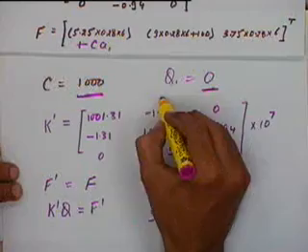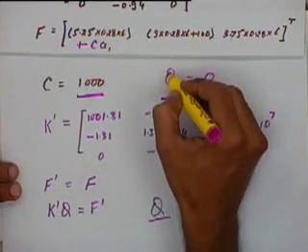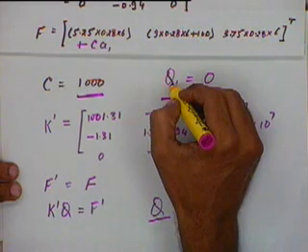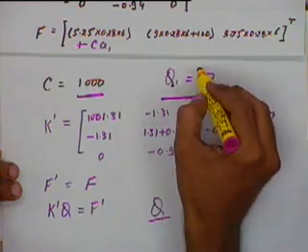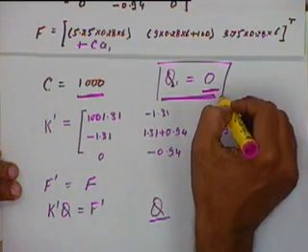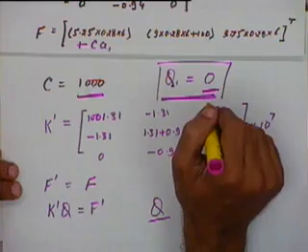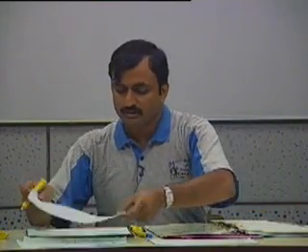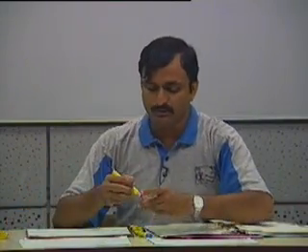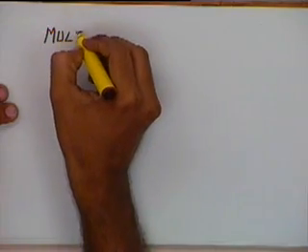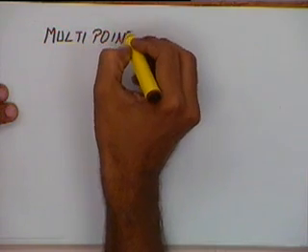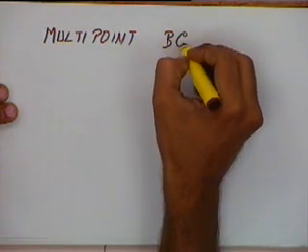These are the single point boundary conditions because these are giving constraints on only one node at a time. Q1 is a deformation of one node. This constraint is giving a deformation of only one node or is controlling a deformation of only one node. So we call them single point boundary conditions. In contrast to this, we will now see what are referred to as multi-point boundary conditions.